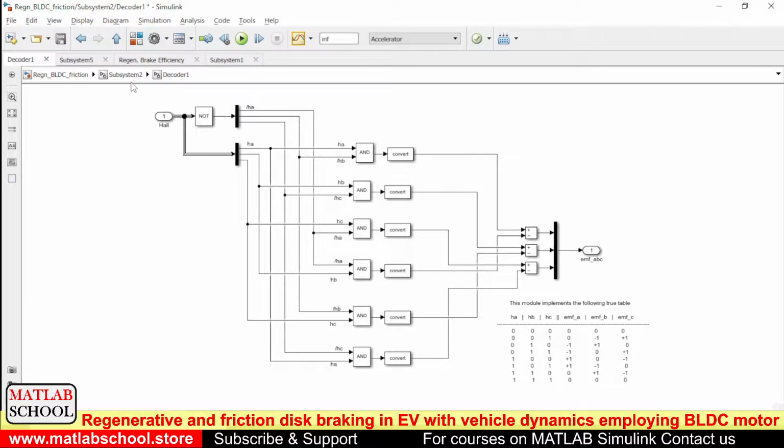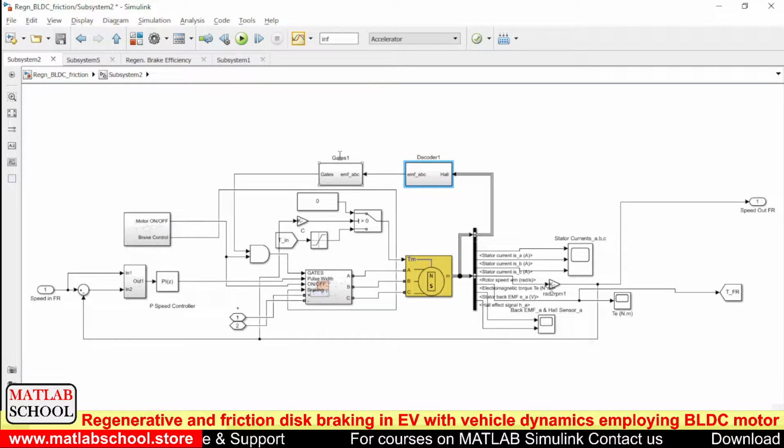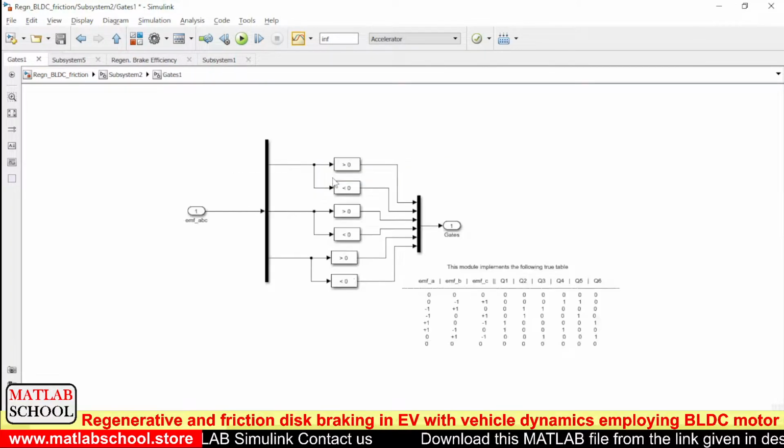Okay, and the output of this block is given as input to the next stage, where the gate signals are generated based on the EMF position or EMF values. Okay, so as you see, the EMF values are converted to gate pulses. Q1, Q2, Q3, Q4, Q5 and Q6 correspond to the 6 switches in the inverter.